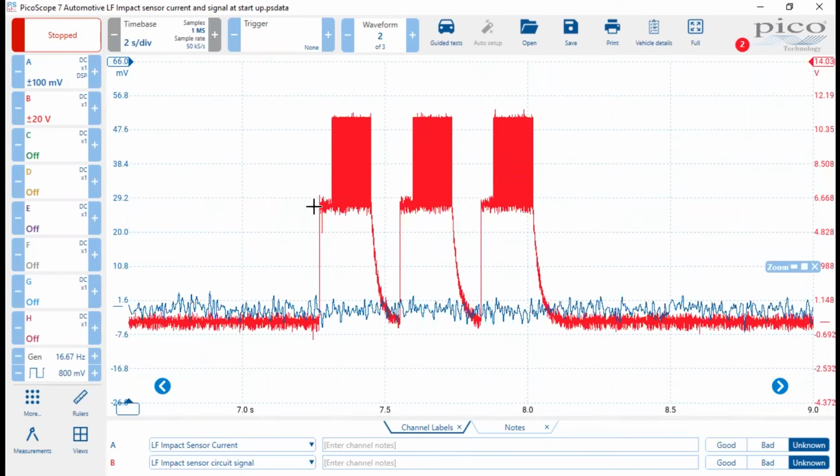But if you take a look at it, my voltage signature is the same as before, but there's no change in the amperage. And all that means is there's no current flow in this circuit. So what I've got here is a situation where I've got voltage being applied, but no current. Now, the only way that can happen really is if the circuit is incomplete. So I know I don't have a wiring problem. At least I don't think I have a wiring problem.